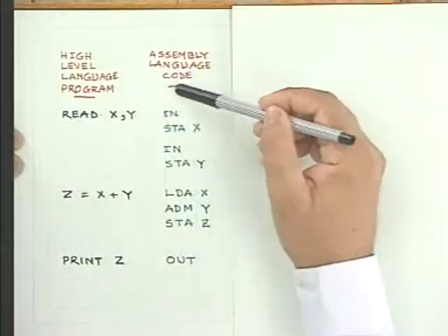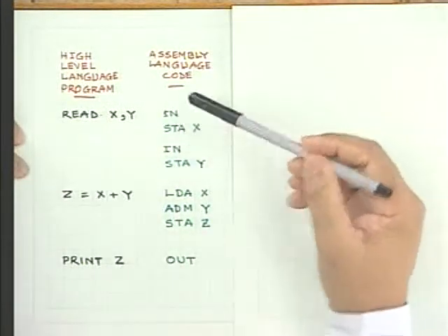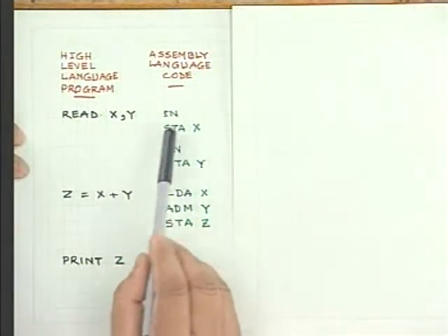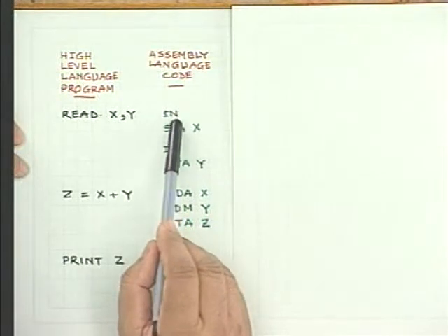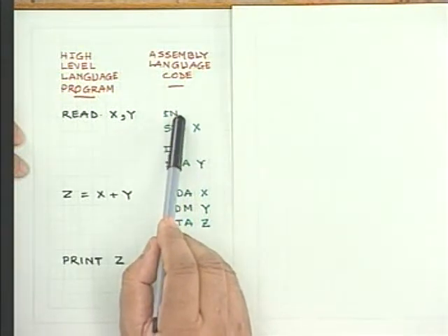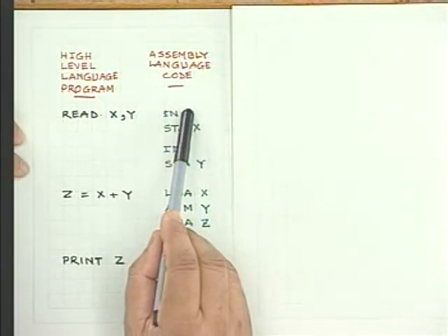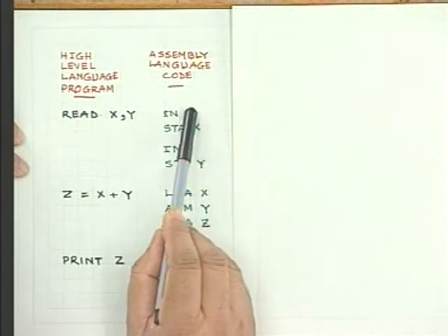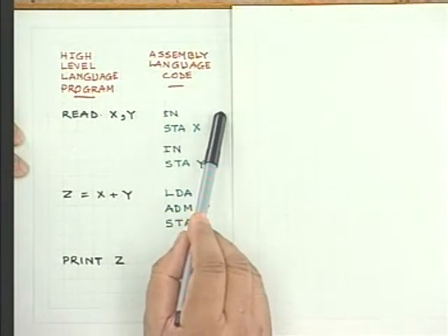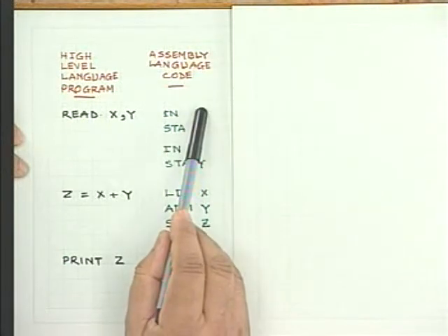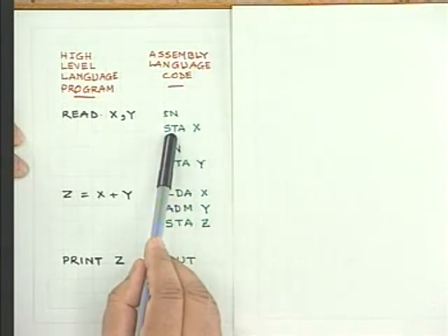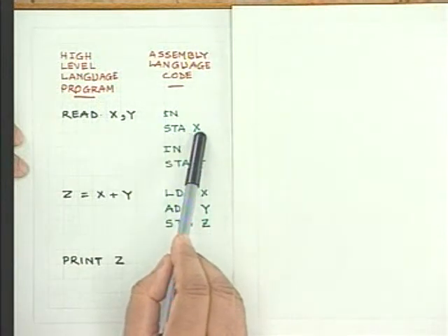Now, let's come to this assembly language program once more. I'm assuming that there's only one input device. It is inputting a value of 2 bytes into the accumulator, then it's storing that accumulator value into the location x.